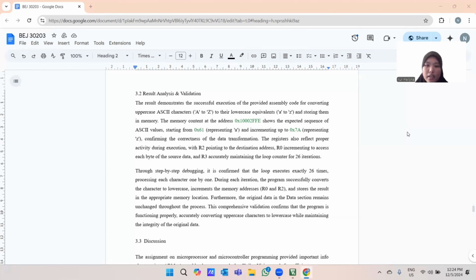Proper memory allocation and addressing mechanisms ensure reliable data transmission. Assembly's addressing modes are vital for efficient memory access and modification. The loop uses instructions like LDRB and STRB to load and store data. Termination conditions and address increments ensure correct looping for all 26 letters. Assembly programming provides precise hardware control, optimizing memory use and performance.